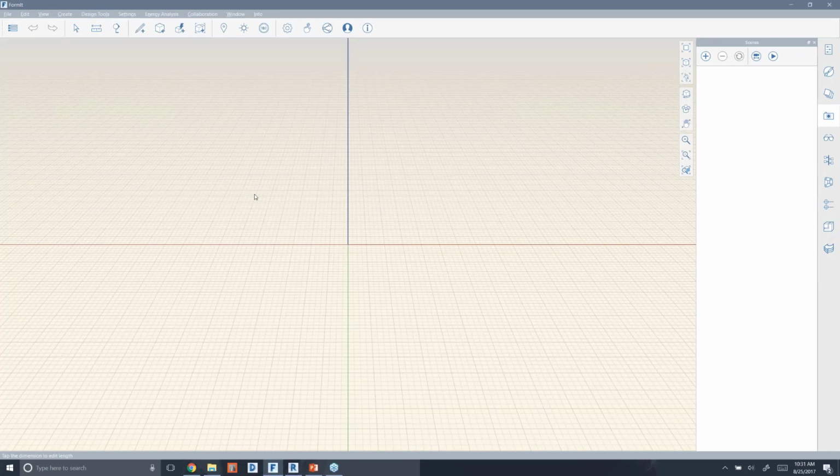And what I'll show you is that if you do a Control V at this point, so we're pasting from our clipboard, I'll have the window itself on my cursor, and you can see the placement point is at the bottom center of the face. And we'll talk about that in just a moment, but it's the same concept of this XYZ axis. It's just for this group, its origin point is the bottom center face. So I can click and place that wherever I want.